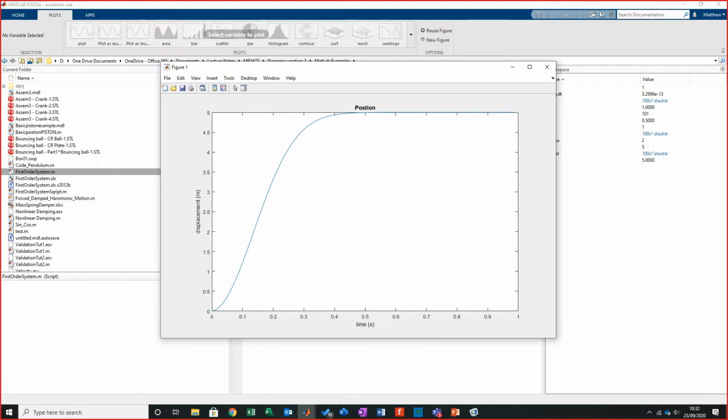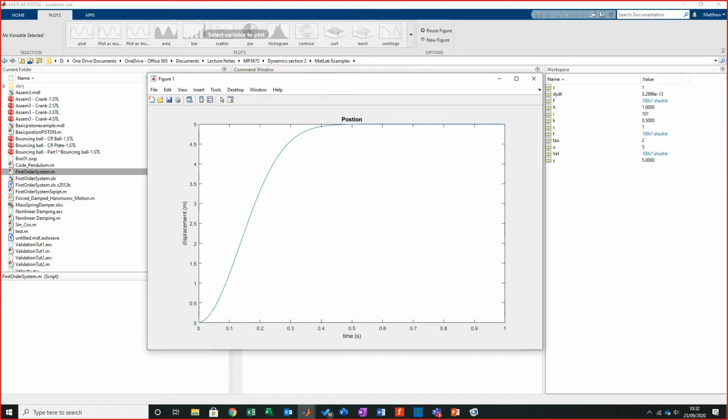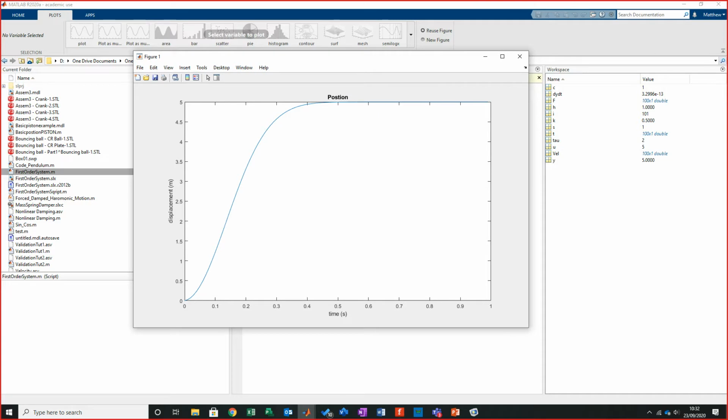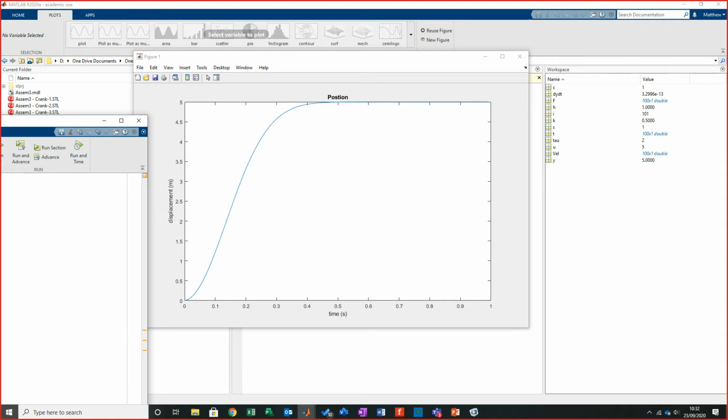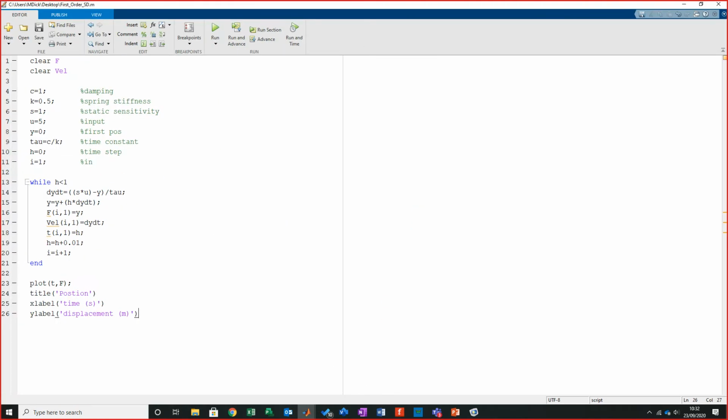So what we could do is drop that damper strength and then look at its behaviour. One thing I'm aware of though is this is just position. This is just where it's moved. I don't really know how quick it's moved, and that's really where I want to go next. I want to plot the dy by dt. I want to plot that velocity, and I just want to see how quick this thing has moved. So what I'll do again is I'm just going to type figure.